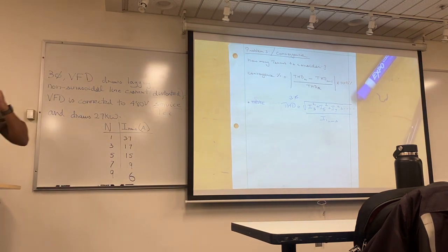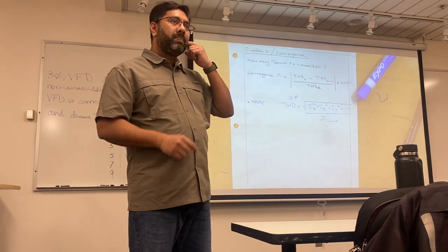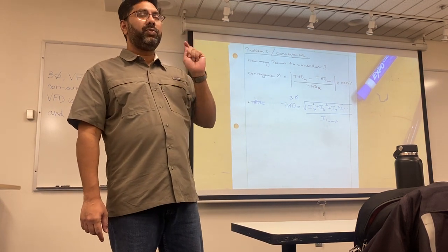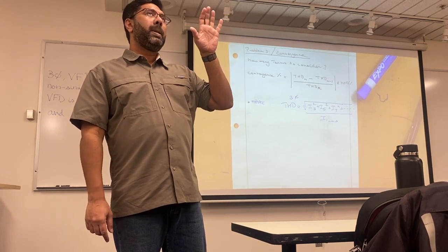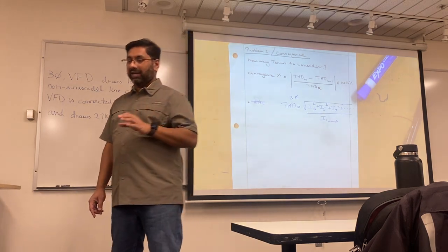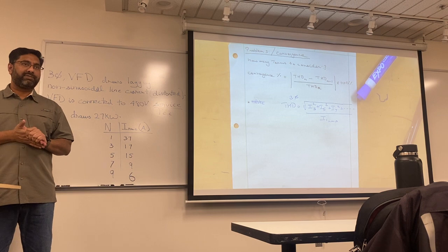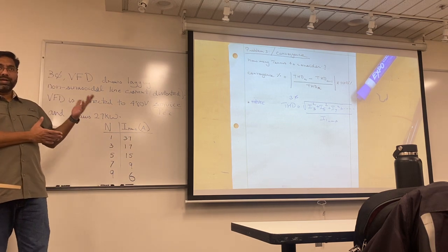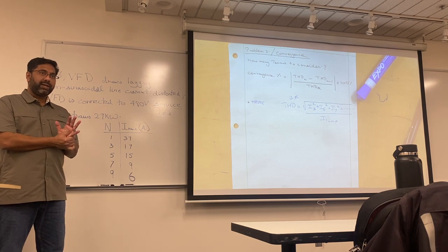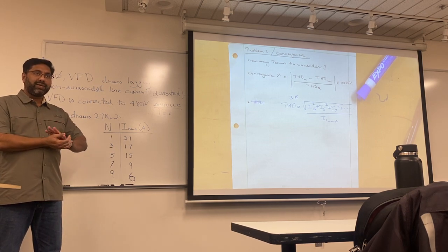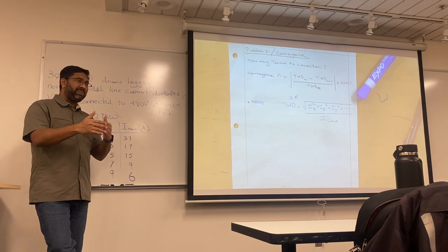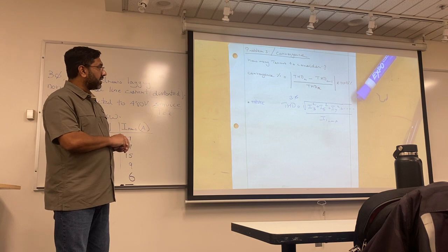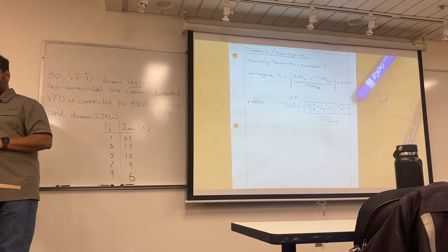With the triplens going over the neutral, is that something that we just deal with, or do we try to prevent that with filtering? You try to prevent it by filtering, and we tack on a certain dollar amount to your bill. Older customers who have several-year-old devices will rather take the fine than do anything about it. And we are kind of screwed because our neutral is heating up, and our transformers are getting burnt or overloaded. So we have to deal with it. We have folks who know how to talk nicely and get them to agree to some sort of payment plan where we put in half, they put in half. Does it affect efficiency at all? Yeah, transformer heat, efficiencies are, oh my God. Circulating currents are a big deal, especially when there's a fault, it creates havoc.